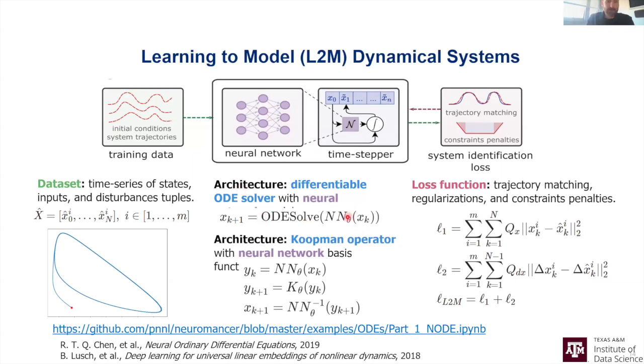So how do we typically train these is that instead of some sampling of the parametric space, we have time series data that represents observations of our system states. And if it's an unknown non-autonomous system, which means there are some control inputs, we also have time series of the control perturbations and then the state response of the system to the control perturbation. And how are we training them?